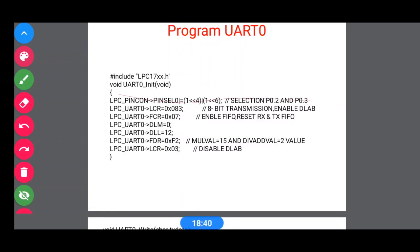To select them, we are using the pin select 0 register, whose 4th and 5th bits are associated with pin 0.2, and it is the first function, so we are setting the 4th and 5th bits of the pin select 0 register as 01.